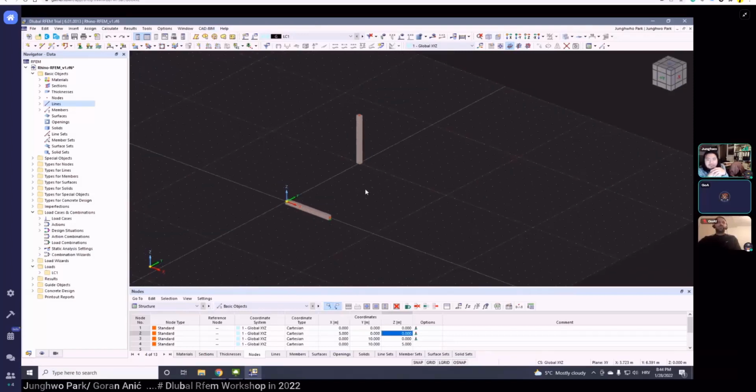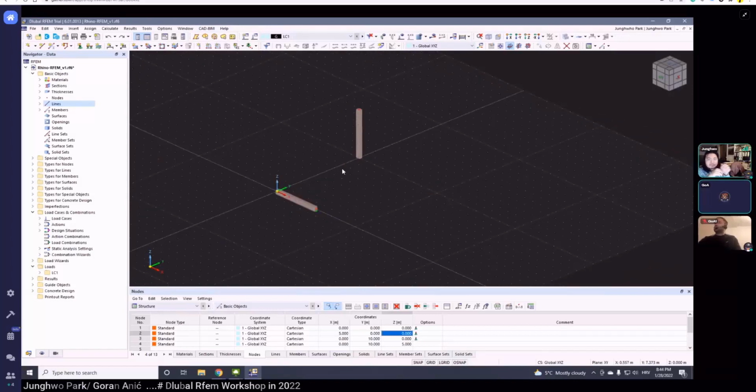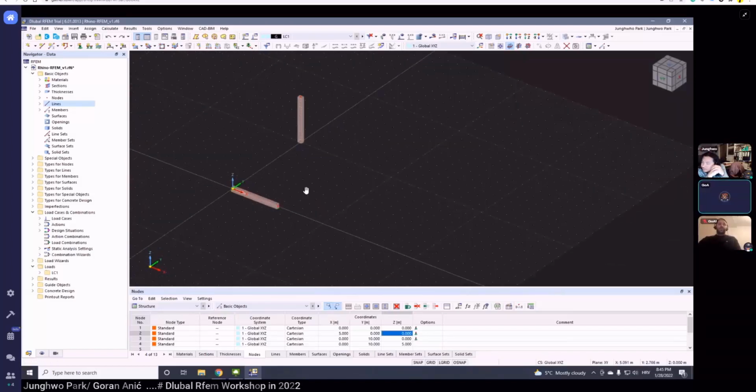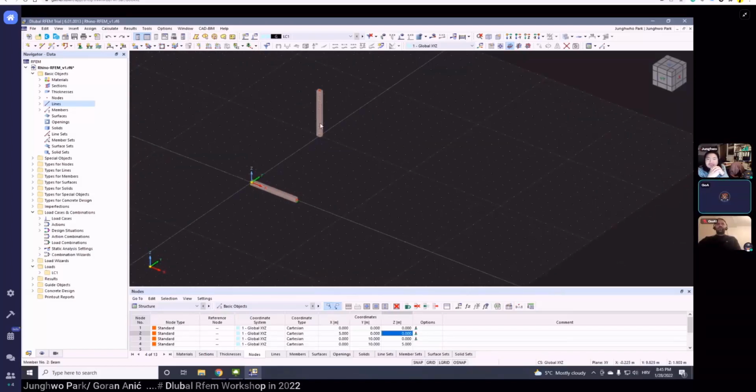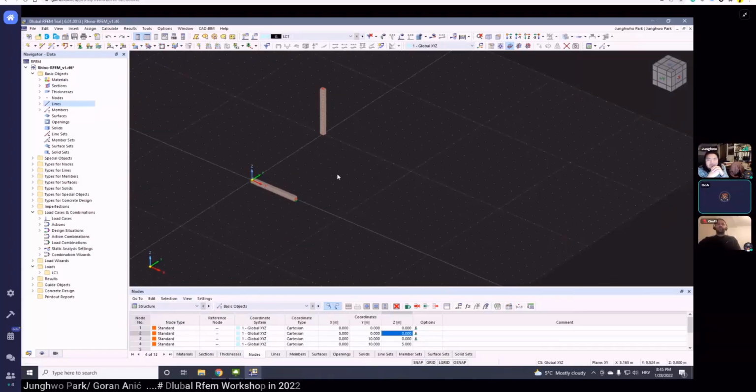It's a very nice option because you can choose the element which you want to transfer into RFEM, like members or surfaces, just by clicking on that element and telling it to convert to a surface. So nice. For the beginning, those are the basic functions for how to create members. It will be important for us when we start creating something in Rhino with Grasshopper.